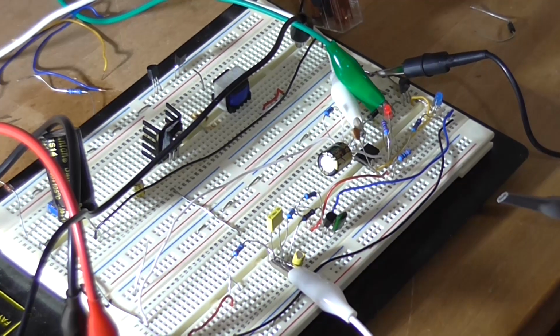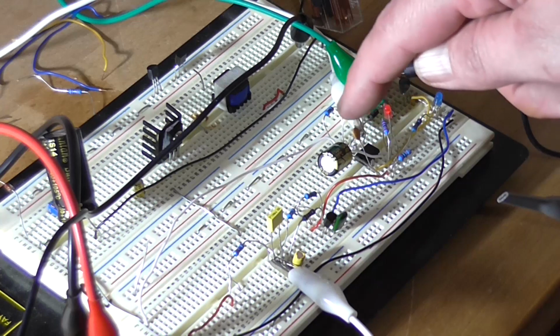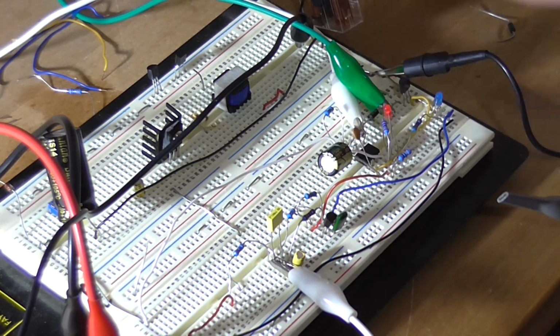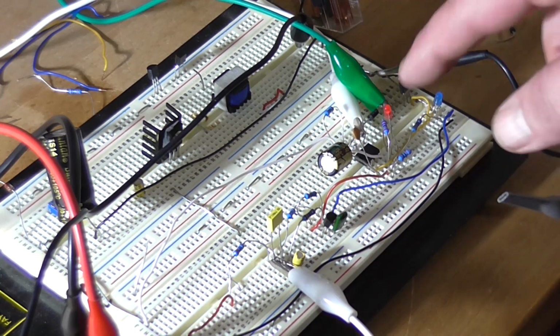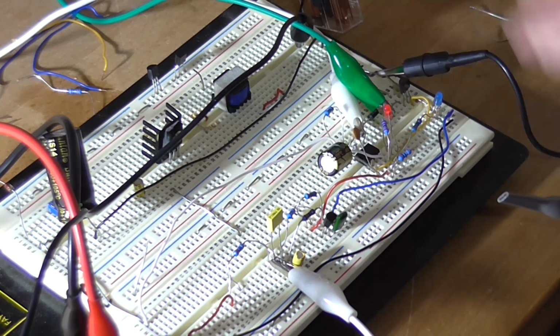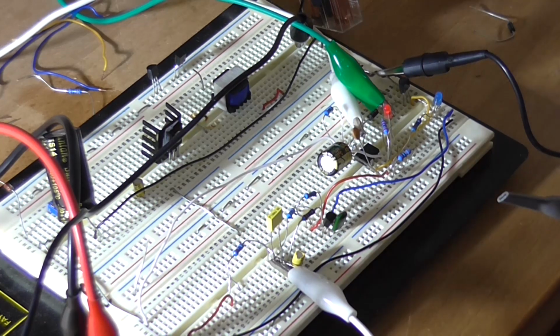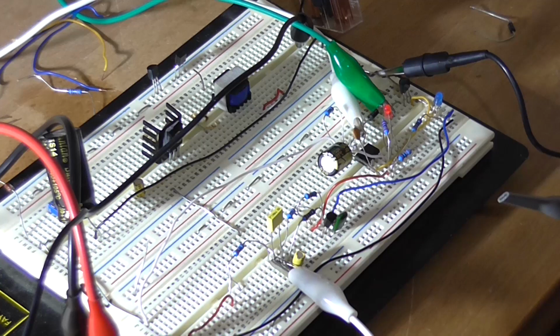I've figured with 1 megaohm and 1000 microfarad, the circuit will stay active for roughly about 4.5 minutes, which is quite a considerable long time. Conversely, if you lower these values, well, the on time will be shorter. However, I think 11 seconds is reasonable for this particular application to keep the relay on long enough to do something.